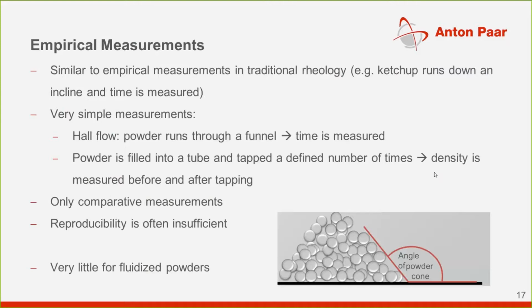There are measurement methods that are very similar to methods that were used or still are used in traditional rheology. So you let a liquid run down an incline and measure the time. This is also done more or less for powders with, for example, the Hall flow meter, where the powder runs through a funnel and the time is measured that the powder needs to run through it completely. One thing that should be mentioned is that this is a measurement that is quite operator dependent. Depending on how the funnel is filled, the powder, of course, will have a certain state of pre-compaction, and so it will flow differently.